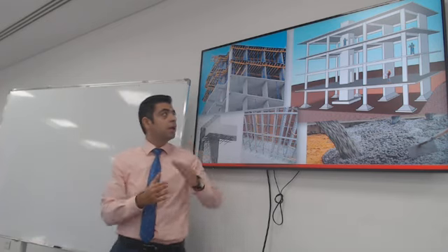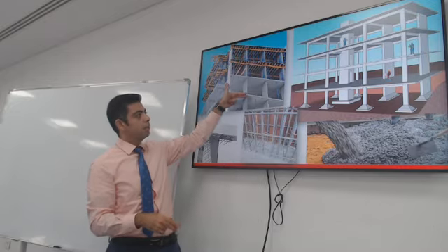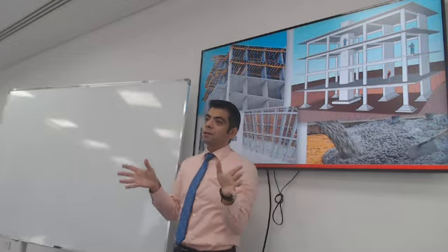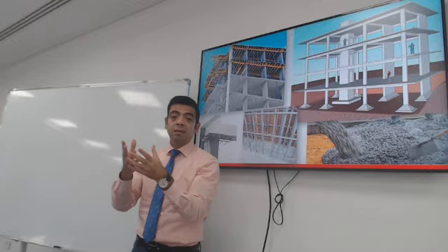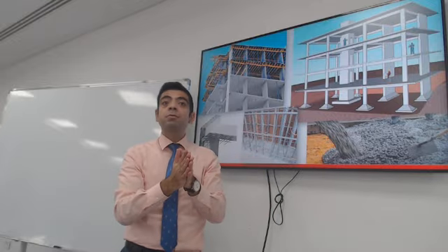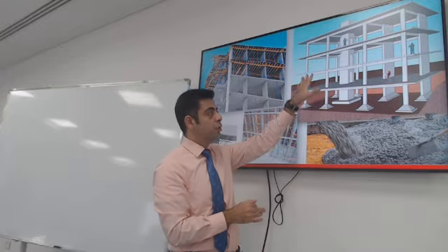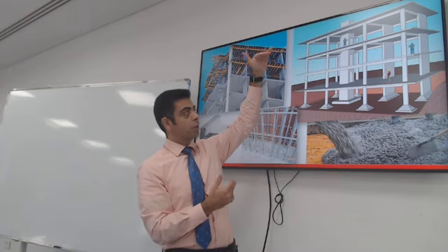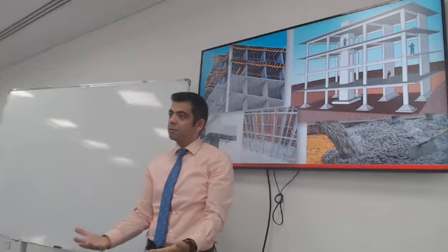You can shape it into a slab. You can shape it into a column, foundation, wall, and then you look at the structure and design each element in order for the load path, for the load transfer, to find its way safely from whatever the load application is to the ground. So if the load is the weight of a person, that weight of the person on the 3rd floor needs to safely find its way to the supports of the structure.